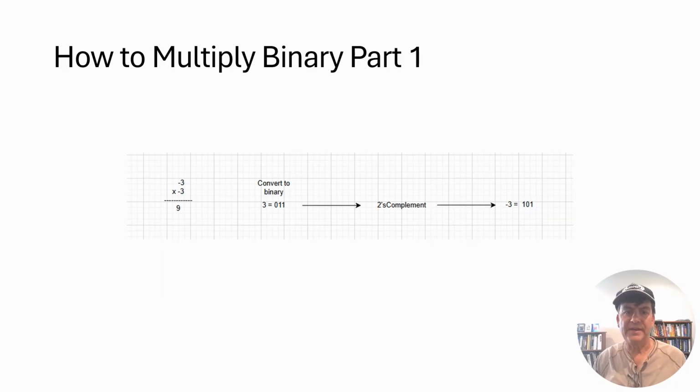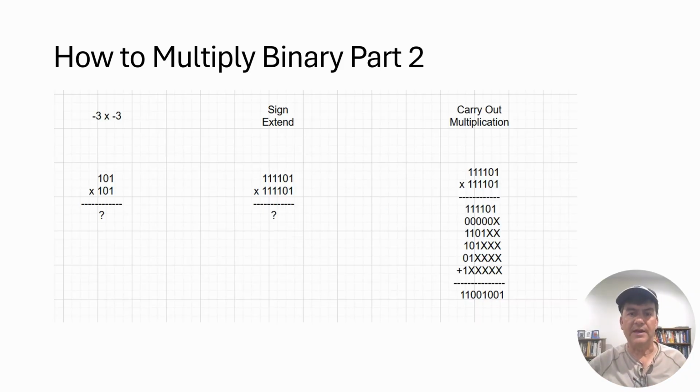Another issue you might encounter is manually verifying the binary result of the mixer. Binary multiplication can seem tricky if you're not familiar with it, but it's actually straightforward once you know the steps. In the slide, we want to multiply -3 times -3 to get 9. First, we represent -3 in 2's complement form: invert the binary representation of 3 and then add 1, which gives 101 for minus 3. Next, the slide shows the operation minus 3 times minus 3.